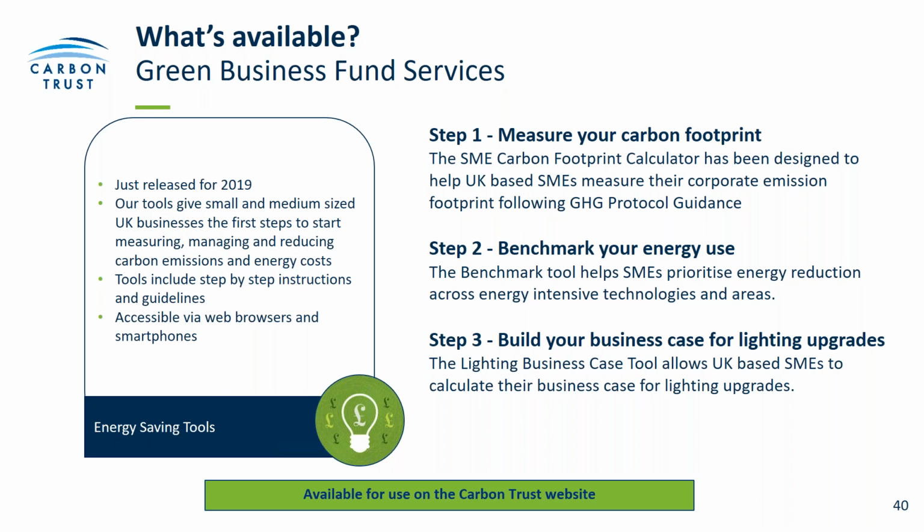So if your organization is still operating either fluorescent or metal halide lighting, then you need to change them out, because it's a very cost-effective project. Now you're looking at a payback, depending on the existing lighting, of between 3 and 3.5 years. So we're more than happy to assist you with that as well.